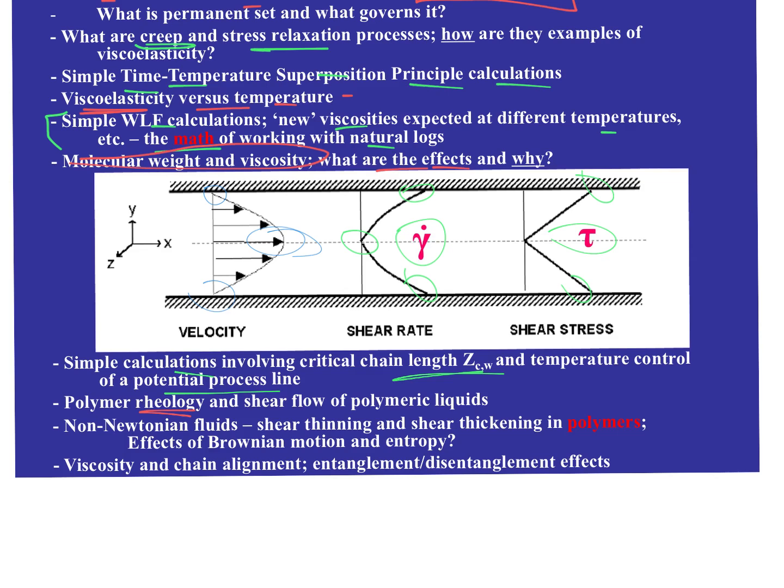And this issue involves, of course, the shear flow of polymeric liquids, because, of course, there's a ton of shear going on up here. And in that context, we recognize that many of these are non-Newtonian fluids. All right, water is our only Newtonian fluid, and it's a wonderful thing to make assumptions about. But in this real world, we're talking about polymeric systems that exhibit either shear thinning or shear thickening.